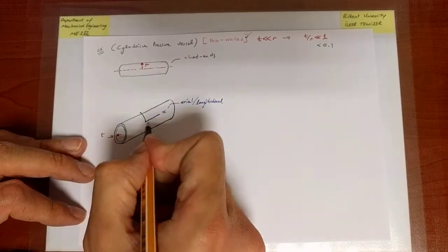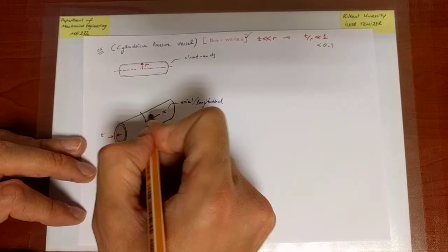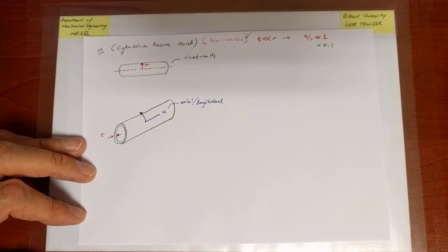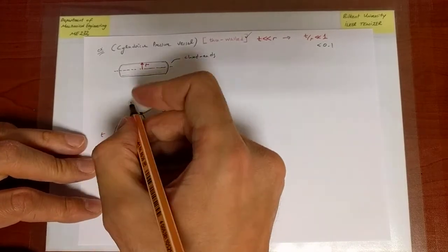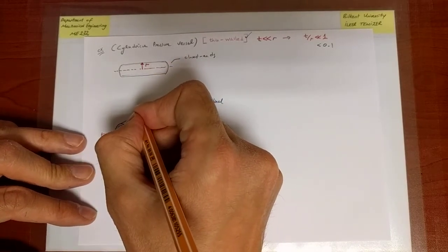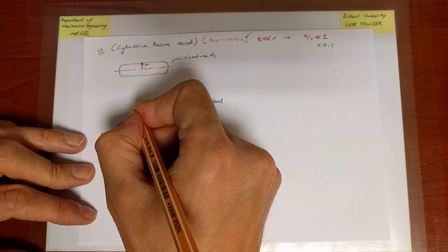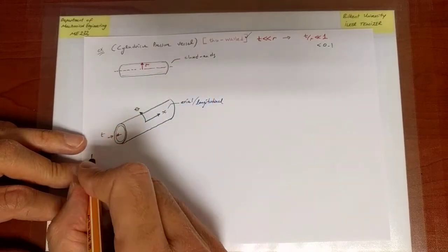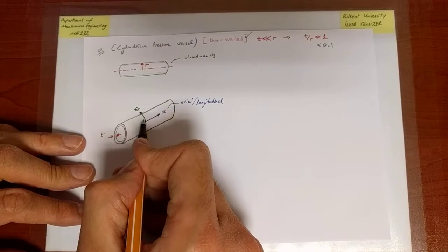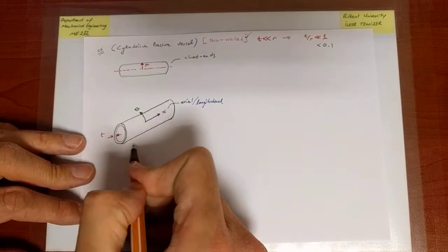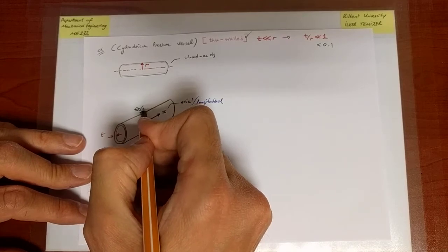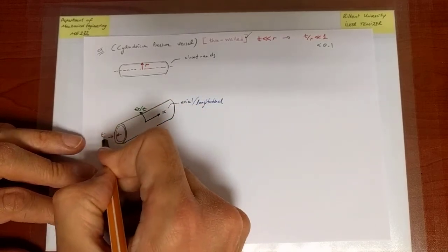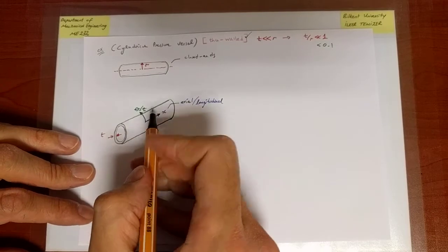That direction which moves around the circumference is going to be called the circumferential, or the tangential, or the hoop direction. So there are several names to it, and it's customary to denote it by theta, because that's the direction that you usually indicate with in a cylindrical coordinate system, but we will also call it t, not to confuse it with the thickness, by the way, right?